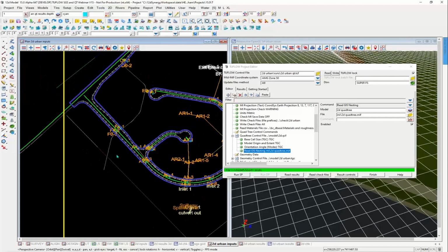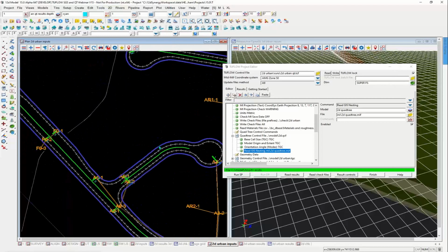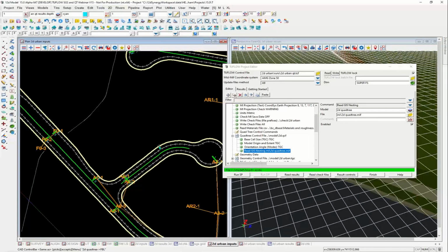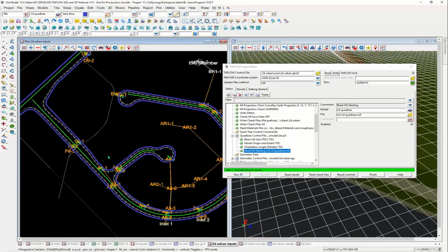So the idea is that if you wanted to put another region in, it's really just a matter of drawing another polygon. So tools inside 12D, I'd use my eyedropper. Because I already have a polygon, I can go select an existing one, and it'll automatically populate my models and all that sort of thing across the toolbar. And then I mentioned earlier on that if you're going to be drawing polygons inside 12D, the way to do it is always with this trace option here, even if you're not planning on tracing.